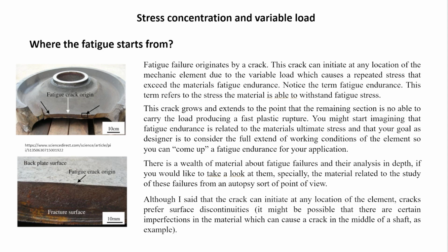So you're going to find out that in most cases, the maximum stresses are going to be found either on the surface or at discontinuity points where the section changes or there is a keyway or something like that, but it's going to be highly associated with the surface. And again, it's going to start there because the material is going to fail at a certain micro spot, and that small failure is going to initiate a crack, and that crack is going to keep growing until the part fails. In a nutshell, that's what's happening with fatigue failure.